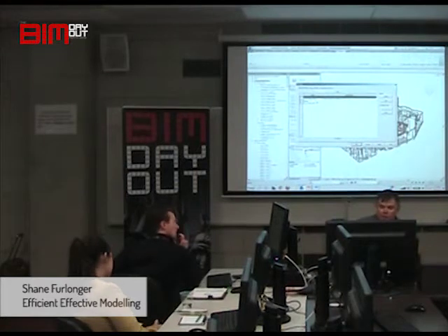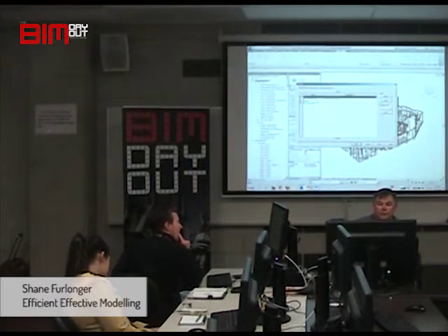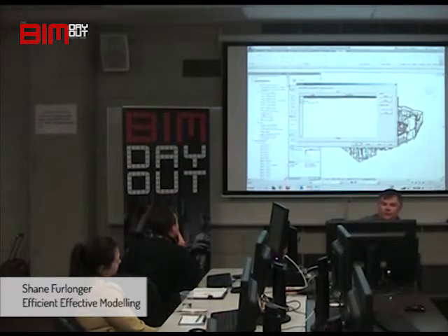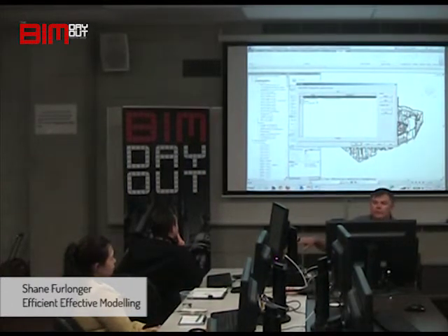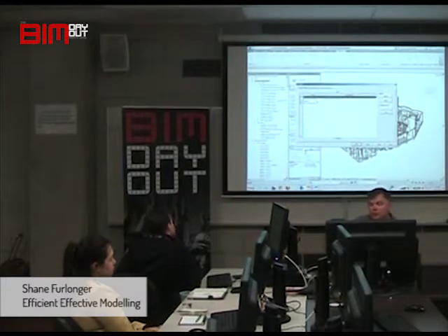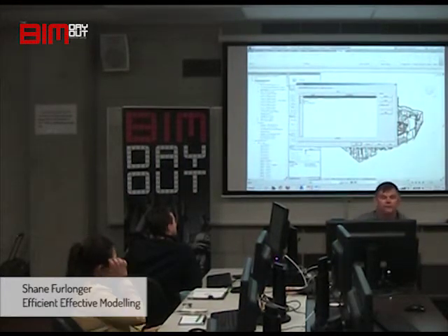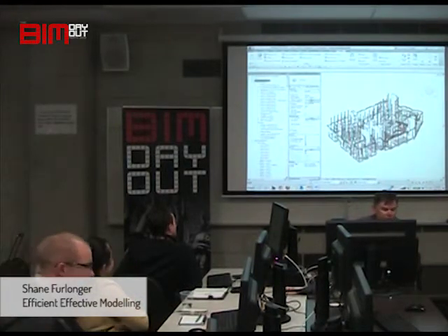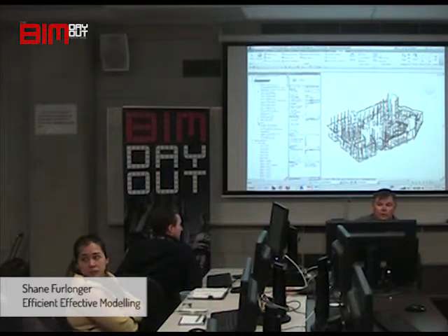So you create this phase and demolish everything you put into it so that it stays within that phase and doesn't get dragged into the rest of your model. So when you're doing your takeoffs for your brickwork or whatever, you'll know that isn't there. You're not double accounting. So I'll just go quickly to the legend phase. I've learnt that off Shane.